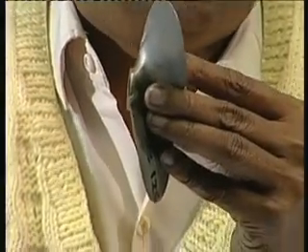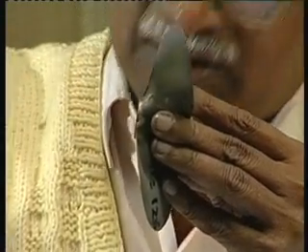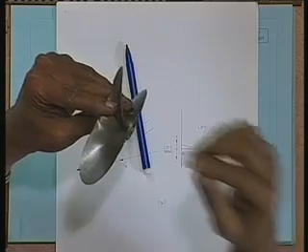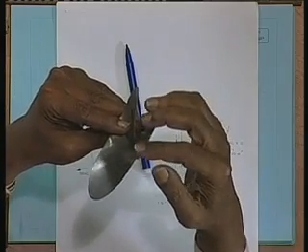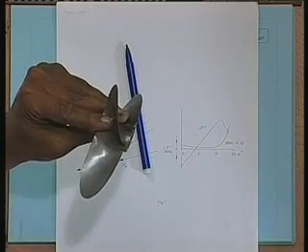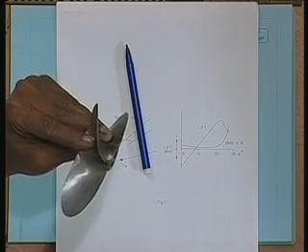Otherwise, what is thrust? How do you get this axial force? This lift that I am getting, the component of that in the axial direction is what I call an element of thrust by any point here. That thrust integrated over the whole blades, all blades, gives me the total thrust on the propeller. Is that clear? I am also losing something in the form of drag. So ultimately, the propeller efficiency will be a ratio between lift and drag. But have you understood how lift is being generated?